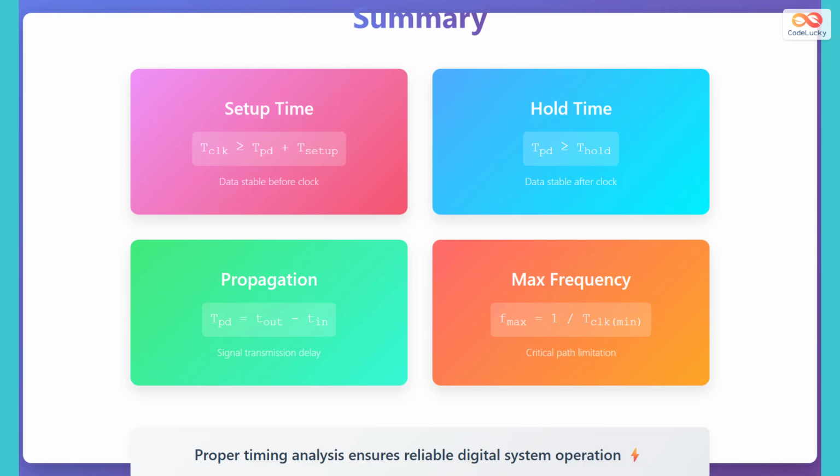In summary, we've covered several key concepts. Setup time, where T clock must be greater than or equal to T propagation delay plus T setup, ensures that data is stable before the clock edge. Hold time, where T propagation delay must be greater than or equal to T hold, ensures that data is stable after the clock edge. Propagation delay is the signal transmission delay, calculated as T out minus T in. Maximum frequency is limited by the critical path and is equal to 1 divided by T clock minimum. Proper timing analysis ensures reliable digital system operation.